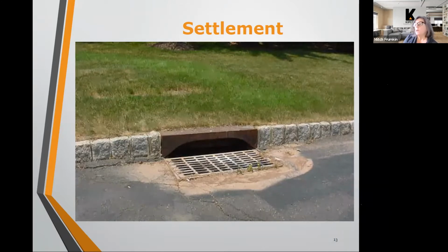So repair of catch basins is often an extra to the project, and we try to capture it in that 15% that I mentioned as part of the extra contingency in that project. So we generally see the catch basin repairs fall within that contingency. In some cases, though, there is so much damage that's so obvious to the catch basins that we will make it part of the base bid for them to be repaired.